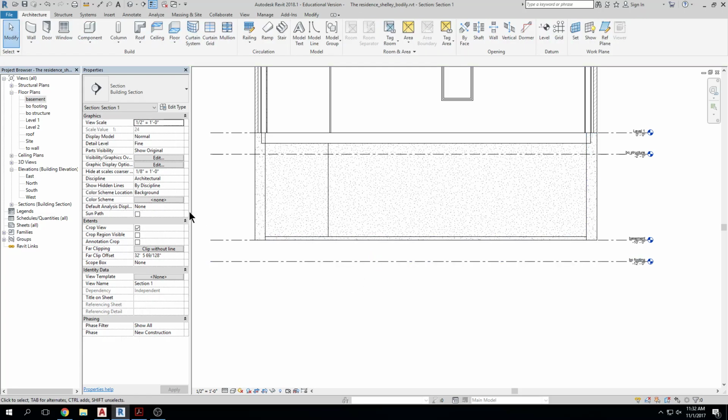All right, so I drew my foundation wall. I think the easiest way to go about it is from level 1, looking down, and they draw that direction, right? And I also think that the easiest way for my basement walls is to open up my basement level and draw my footings from my basement level, right? I've done this all sorts of ways, and again, it seems counterintuitive because you don't see the items as they're generating, which seems weird, but I think all in all, it really does end up being easier.